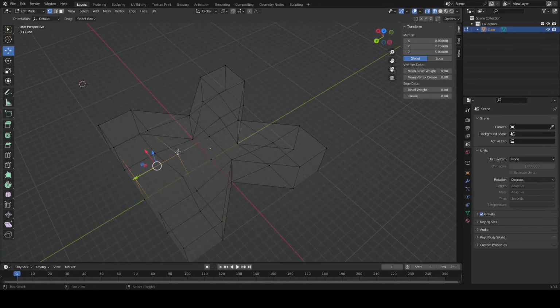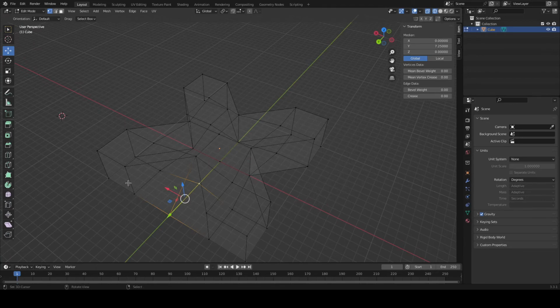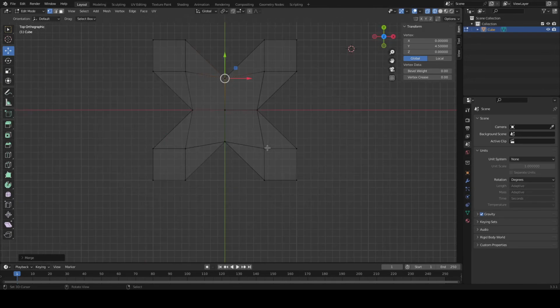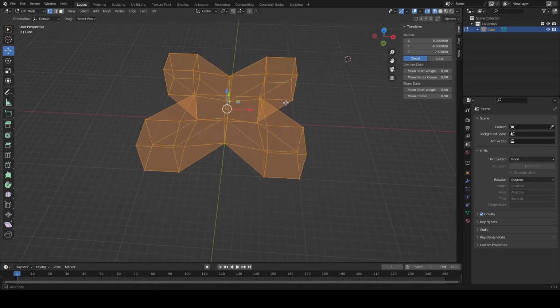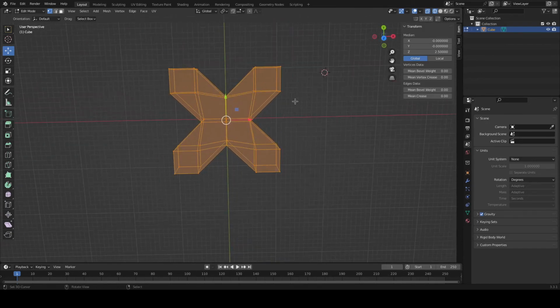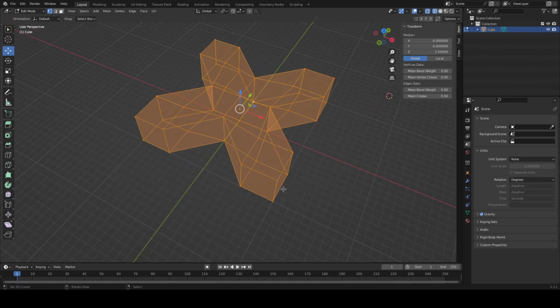And as you have more practice, your brain just starts moving around the scene that you're looking at without you thinking too much about how to do it, because it just becomes an extension of how you think. So here we are. We have now created an X. Now this X isn't actually all that interesting right now because it's kind of pointy, and it's gonna have trouble fitting inside the pockets of our TicTacToe board a little bit. So what we're gonna do is we're gonna round the corners on our cube.